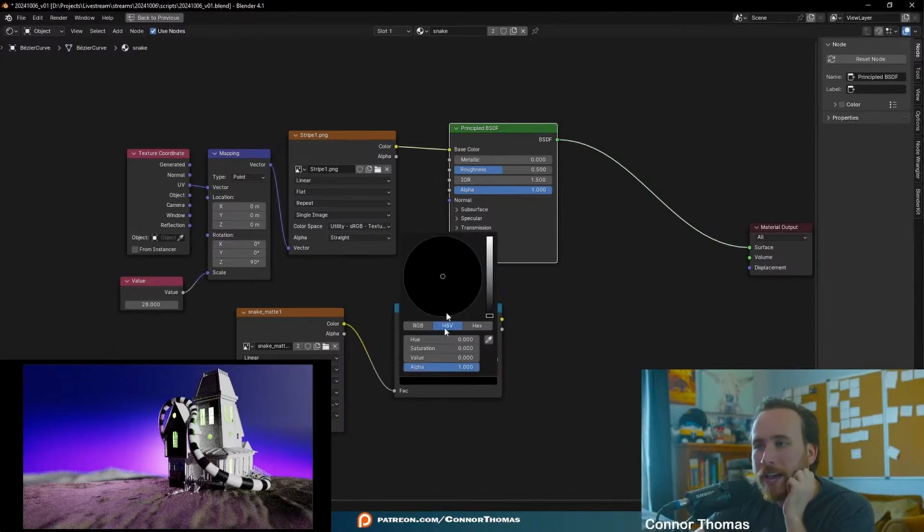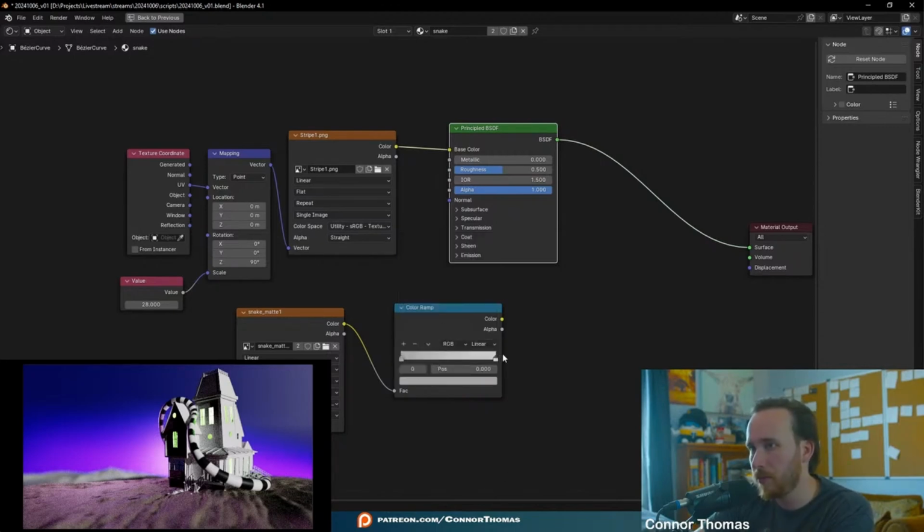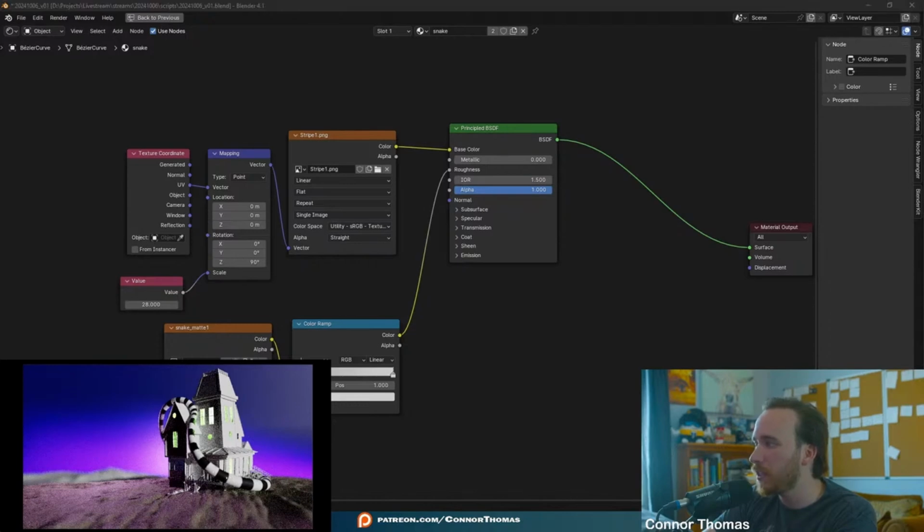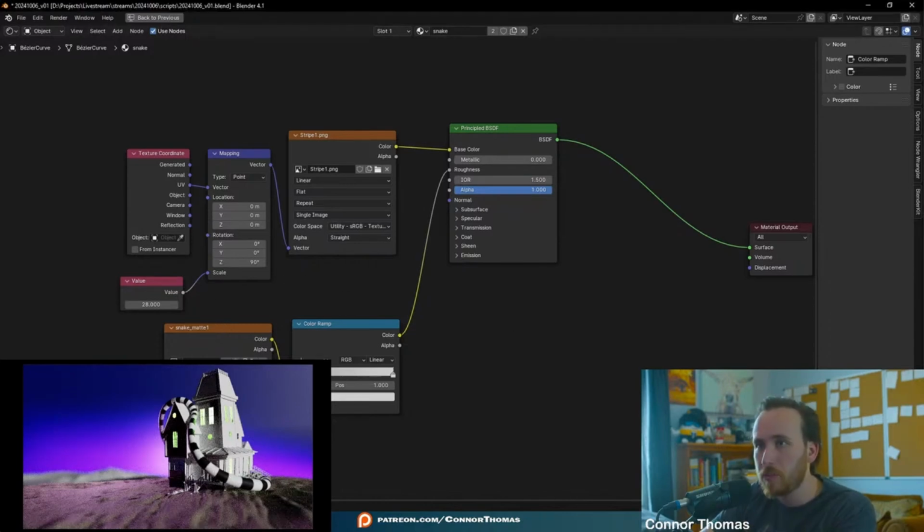Which means that this black here needs to be set to 0.5. And you can set that value here by just typing in a 0.5. That's what 0.5 looks like. And then white is kind of going to be the areas where everything is going to be really matted, and that's set to a 1. But now you just take the color value of this and plug this directly into your roughness, and you're going to have some more specularity adjustments to everything there, but you're not finished yet because we want to use this matte to basically drive our color as well.